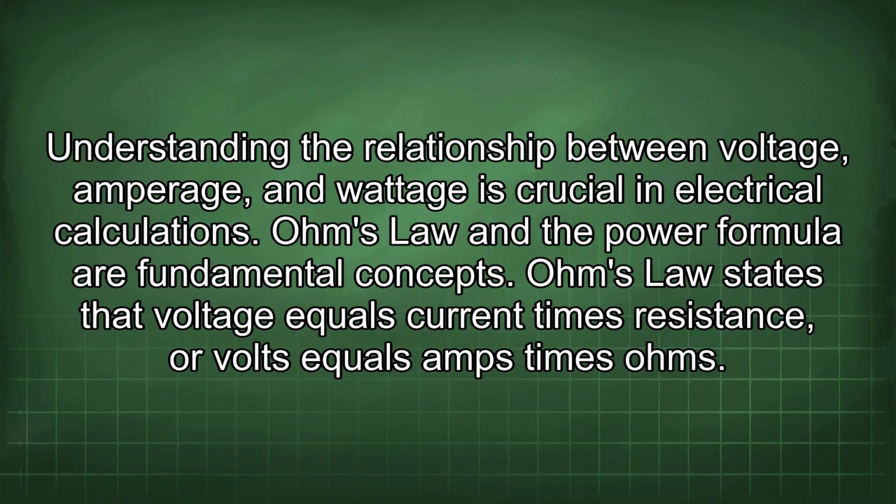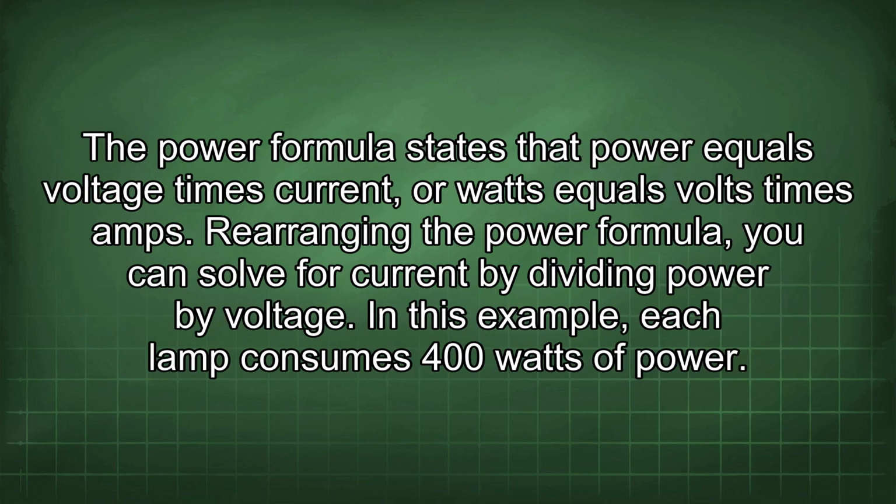Understanding the relationship between voltage, amperage, and wattage is crucial in electrical calculations. Ohm's law and the power formula are fundamental concepts. Ohm's law states that voltage equals current times resistance, or volts equals amps times ohms. The power formula states that power equals voltage times current, or watts equals volts times amps. Rearranging the power formula, you can solve for current by dividing power by voltage.